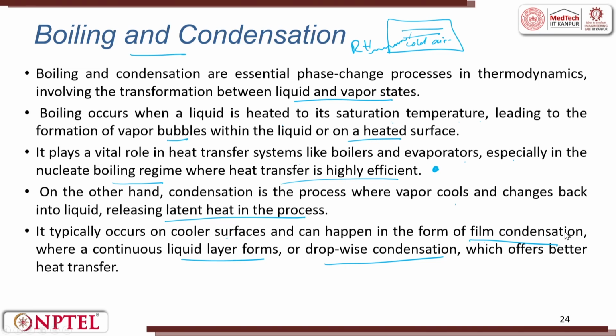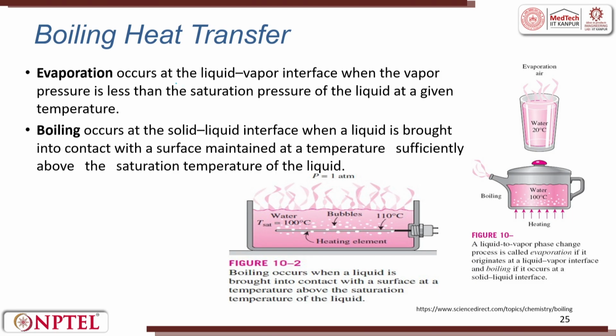or drop-wise condensation. So, evaporation occurs at a liquid-vapor interface where the vapor pressure is less than the saturation pressure of the liquid at a given temperature. Boiling occurs at a solid-liquid interface. Evaporation is at the liquid-vapor interface. Boiling occurs at the solid-liquid interface, where the liquid is brought in contact with a surface maintained at a temperature sufficiently above the saturation temperature of the liquid.